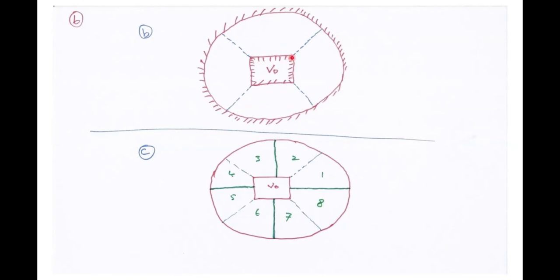That is, the streamlines from the corner of the inner conductor originate and terminate on the outer conductor. So we split the space between the inner conductor and outer conductor into four bigger symmetrical flux tubes. One, two, three, four.